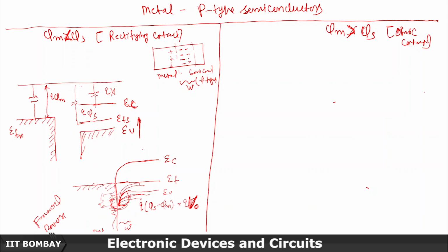So again we got this metal to semiconductor barrier here. Again, how to reduce it? By doing heavy doping towards the p side, so that can help. Basically a large number of holes will be there, so this region will be small enough, right? This region can be small enough. The same technique can be applied here.